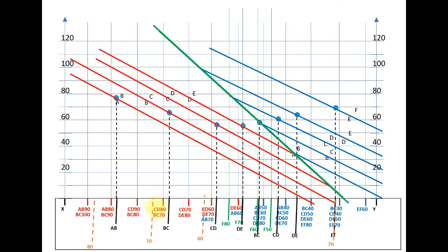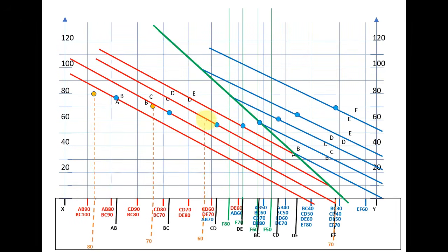The next, we should plot the contour lines. So 80 will just go and meet this 80 point, 70 would come here, 60 would come here, then we directly have here 70, right? So now the points that we need to connect are these points in yellow, in orange and blue that you can see. This will give you the boundary or the top surface of your cross section, and everything that is above that top surface we need to erase.